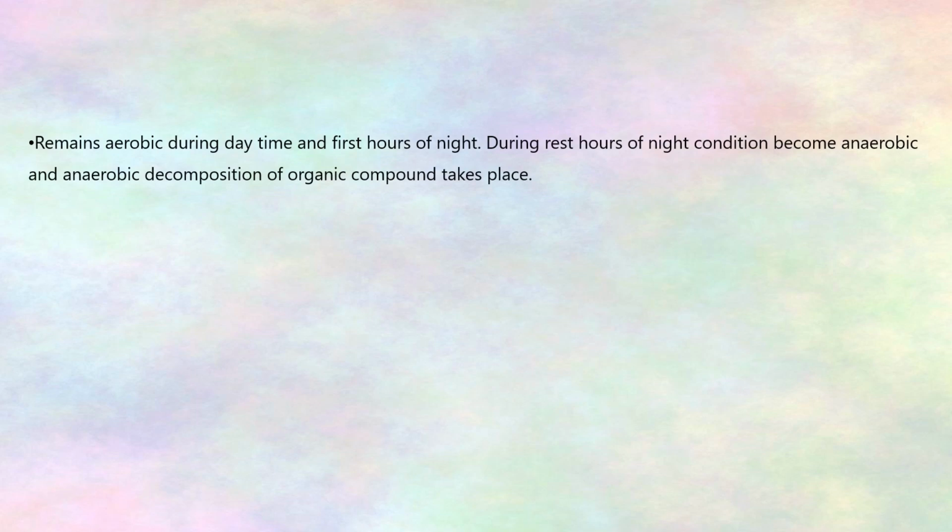The oxidation pond remains aerobic during the daytime and the first hours of the night. During this period, oxidation of organic compounds, that is aerobic decomposition, takes place. During the rest of the night, it becomes anaerobic and anaerobic decomposition of organic compounds takes place.